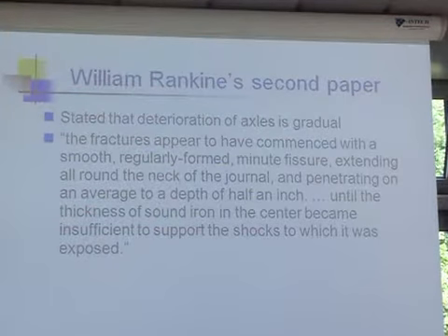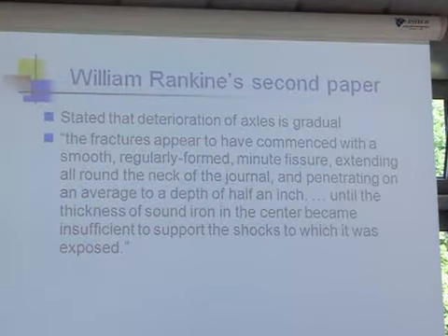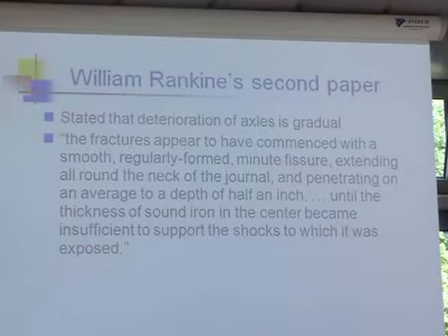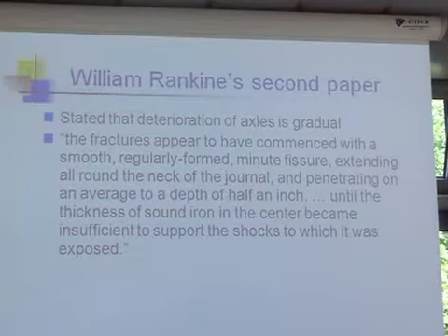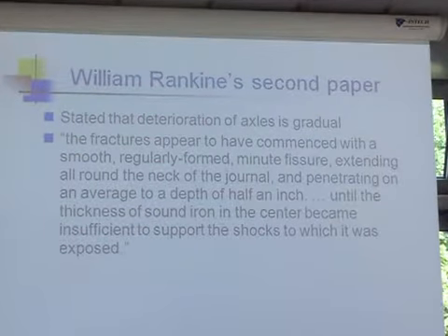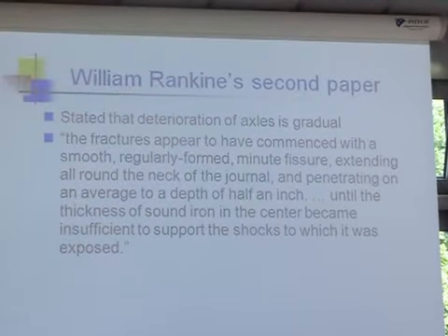And here is his description. The fracture started with a smooth, regularly formed fissure, literally translation from the French for crack, extending all the way around the neck of the journal, rotating, bending fatigue as it goes down the track, until it reached an average depth of about 1/2 inch. He looked at the fracture surfaces to see.